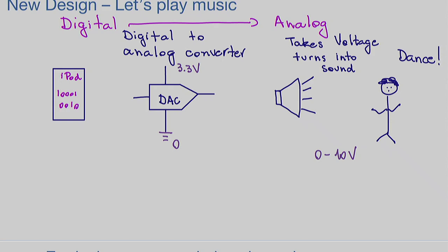Wakey, wakey. Thevenin or Norton? Thevenin. I like Thevenin too. It has a voltage source. I gave you voltage values. It has resistors. We saw that the DAC has many resistors. So I'm going to say that the equivalent circuit for the DAC is going to be a voltage source that is a signal, right? Remember, we started using voltage sources squiggly, but we still call this voltage source V Thevenin.